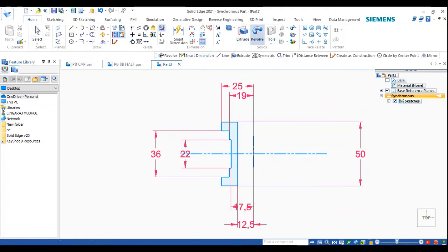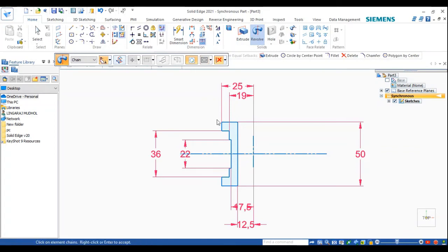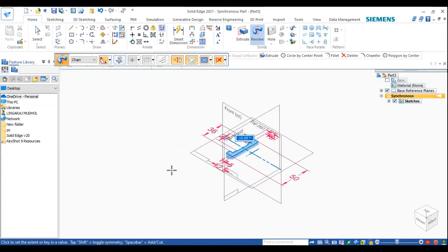Click on it. So again we'll do the revolve for this one. Here it is asking the axis, from which axis you want to revolve it. So this will be our axis. Come back, see, our fourth part should be 180 degrees on the upper part, so 180.